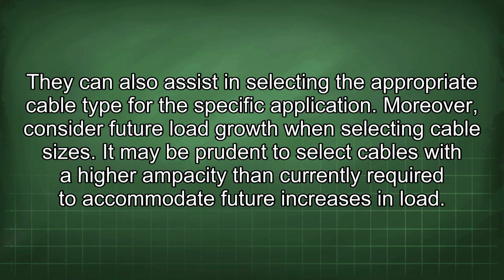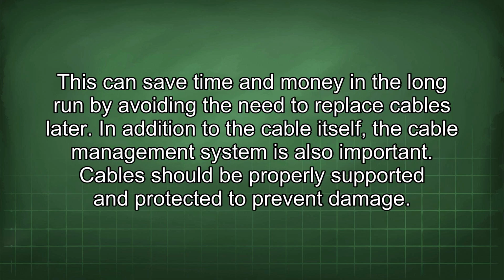Moreover, consider future load growth when selecting cable sizes. It may be prudent to select cables with a higher ampacity than currently required to accommodate future increases in load. This can save time and money in the long run by avoiding the need to replace cables later.